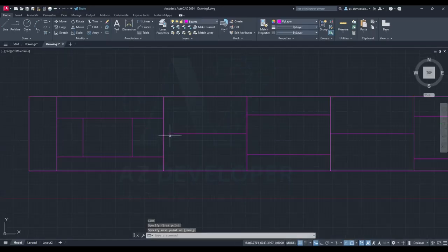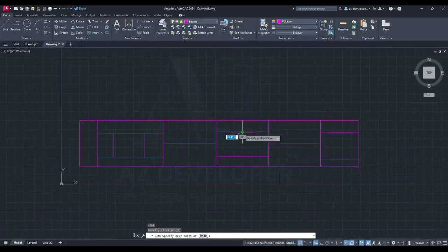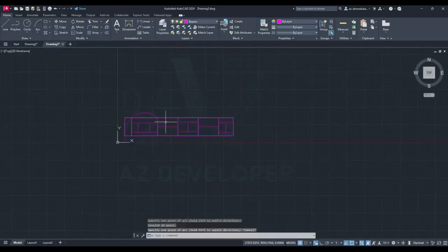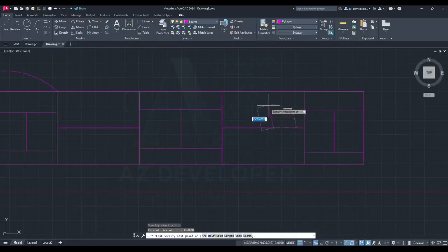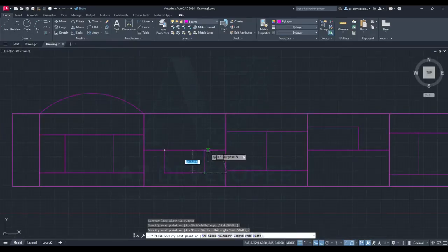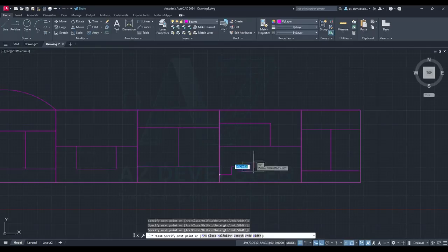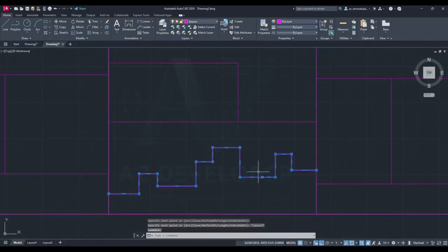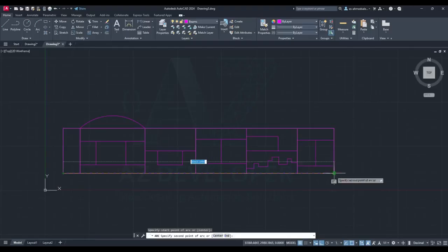Once your plan is ready, save each one as a separate CAD file. There are two requirements. The origin point of the CAD file must match the Tekla model, especially if you want it placed in the correct location automatically. You can always move them later if needed. The file name of the CAD drawing should be the top of steel elevation for that plan, using the same units as the CAD file and Tekla model. You can save the files as DXF or DWG.